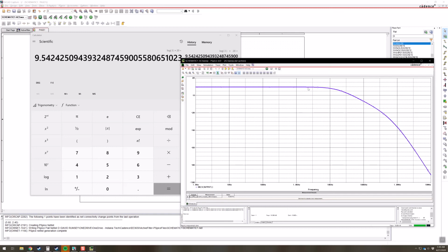And so the key thing I'm wanting to point out is that the minus 3 dB that it's computing is still correct, it's still your cutoff frequency, it's still half power at 15.85 kilohertz. It's not literally at minus 3 dB because in this case the minus 3 dB point would be at roughly 6.5 decibels, because that's 3 dB down from the maximum decibels. Okay?